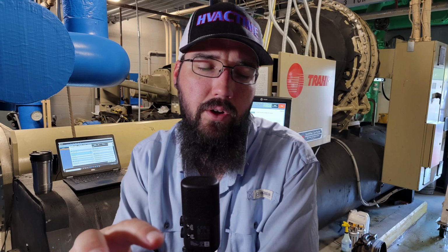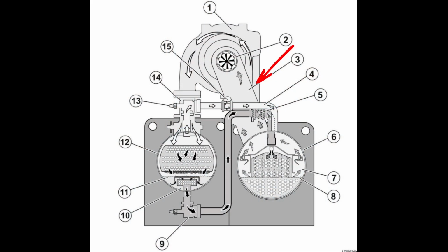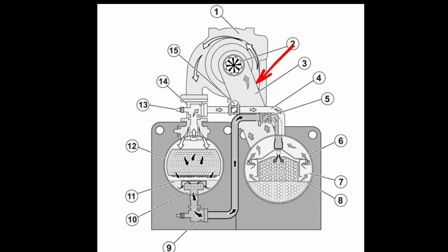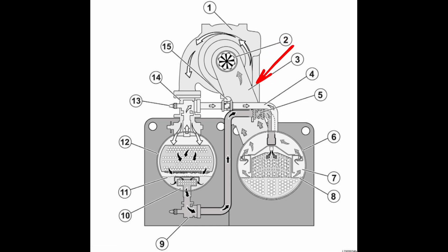And this is also true across any system. So whether it's a shell and tube DX or a flooded shell and tube, for the oil to get recovered without doing it manually, which is a painful process, you have to be online and in operation for that to work. So looking at a hybrid falling film, an example of this, YK shows us a hybrid falling film.